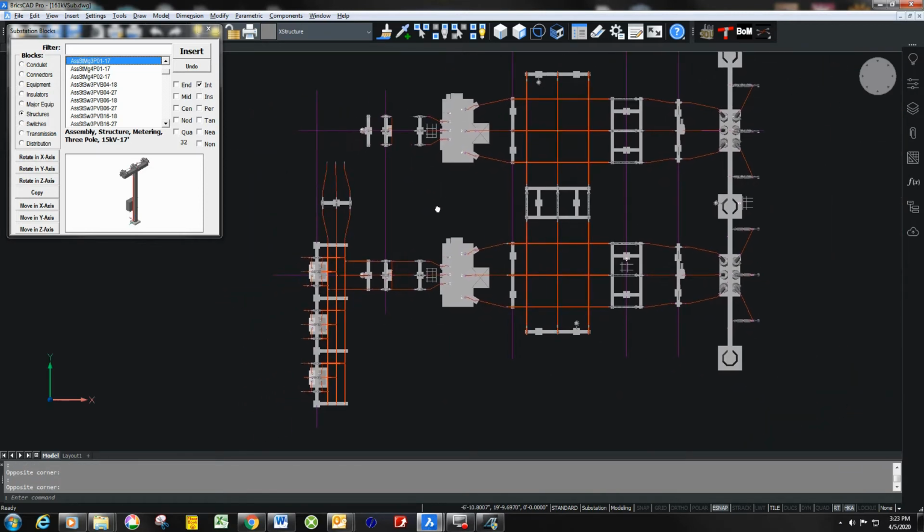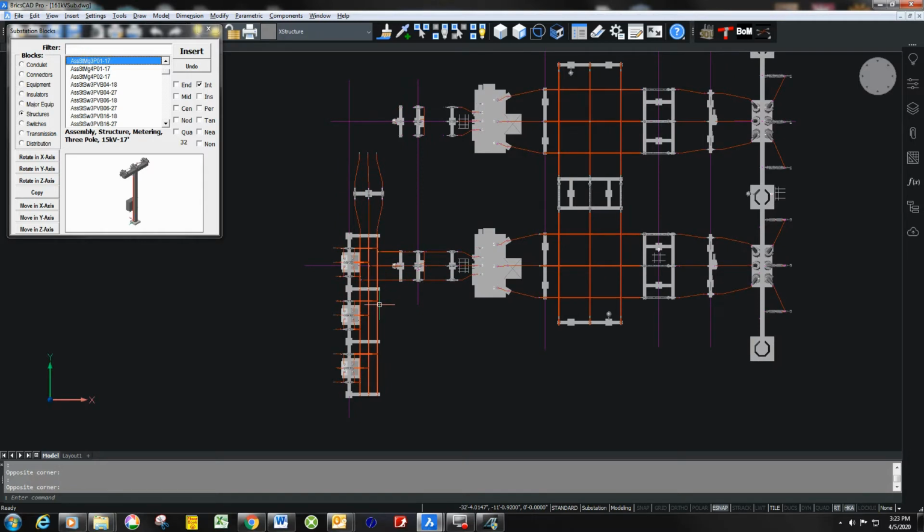So now let's go look at these low side structures. Let's start over here with this one. This structure, if you can see here, is an assembly. It's a structure breaker overhead T1101. So let's just go up here and look at that. T1101 is a full bay. Again, as we were looking, it's got your bus over bus, your overhead